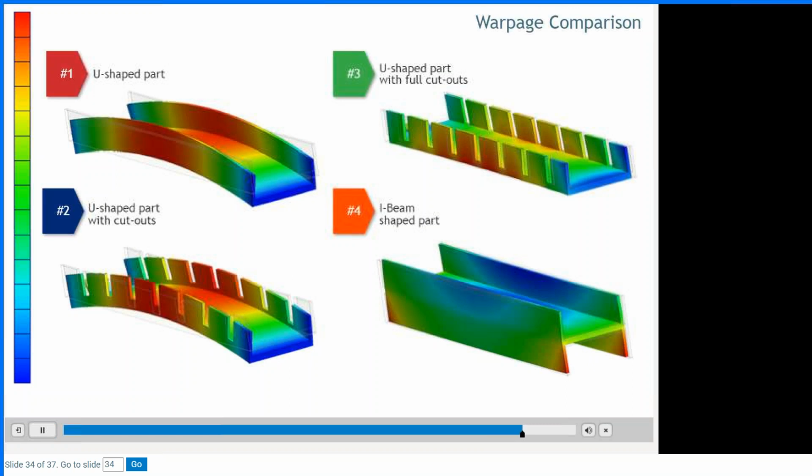On screen, you can see the warpage results of the 4 designs. Clearly, the warpage behavior changes significantly based on the design. The volumetric shrinkage range differences in the base and upright walls are so large that the part warps. The design components must be allowed to shrink freely. So by creating cutouts that extend to the base or changing the upright wall design, the warpage was minimized. This proves that design matters.